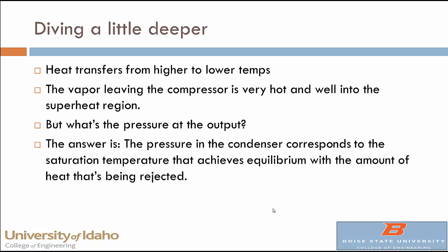Okay, so now we kind of know why evaporative condensers are better: they take whatever temperatures we're stuck with in the environment and allow you to access a lower temperature environment to reject the heat into. And we know that that's good because heat is driven from higher temperature to lower temperature, right?